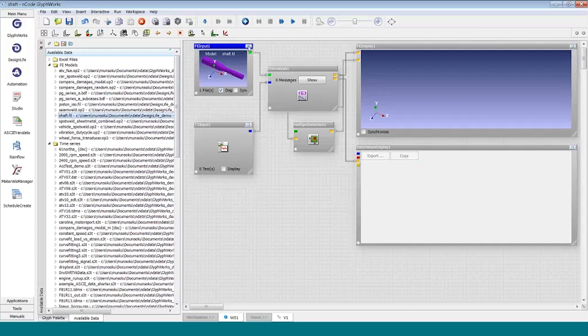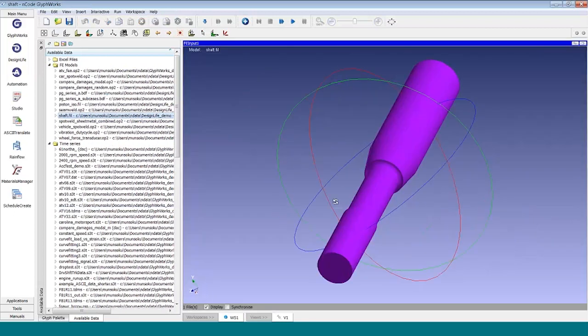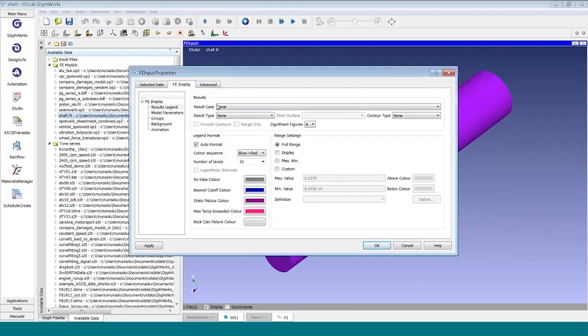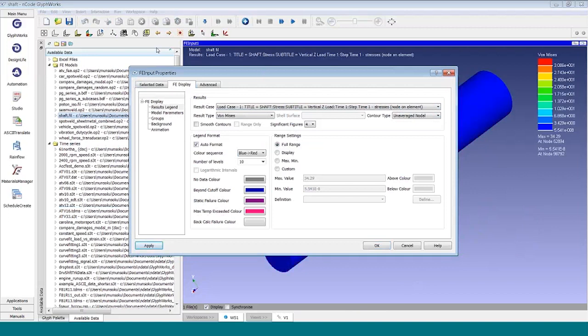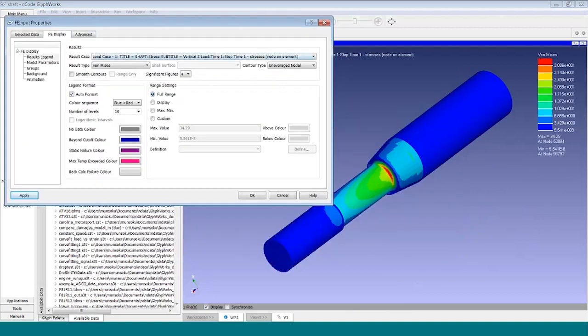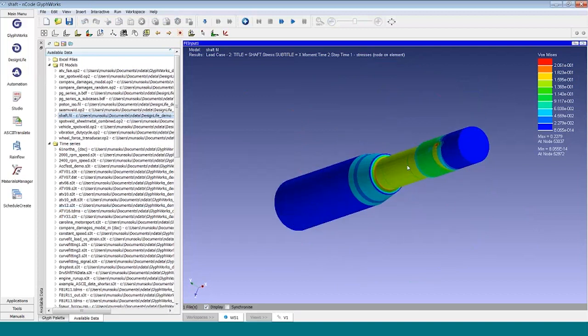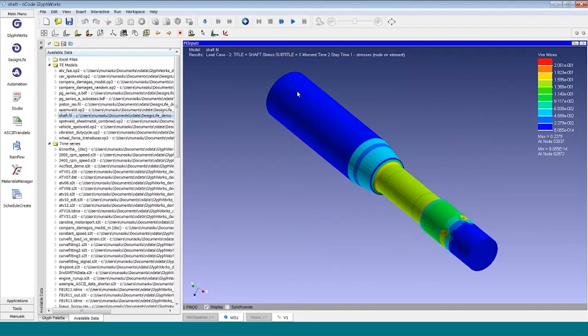One of these is the vertical Z load. Let's see the stresses like this. So that's the unit load of hold one end and push on the other. The second load case that was solved is this one, which is, as you can see from symmetry, hold this end and then twist this direction. So 2 separate load cases were solved. Those are static stresses, so fatigue is not going to be a problem then, right?